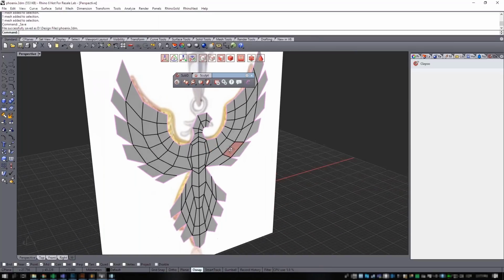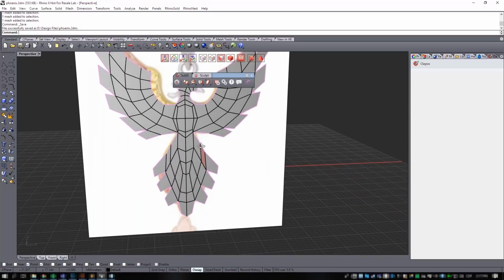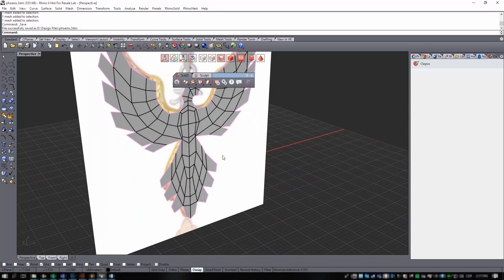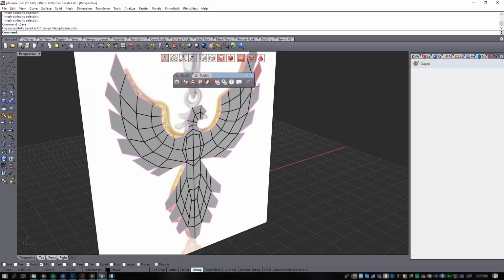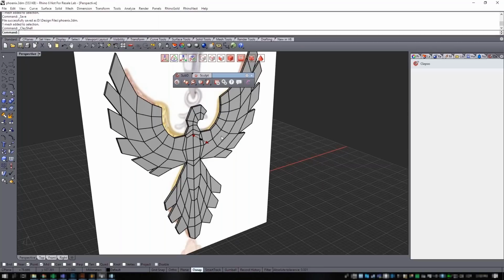Okay, so right now it's the moment where we have to create all the extrusion for my model. So what we're going to do, I'm going to select the entire object, go to the Edition tab here, and go to the Shell tool, this tool here, or you can click G on your keyboard. Let's click this tool.